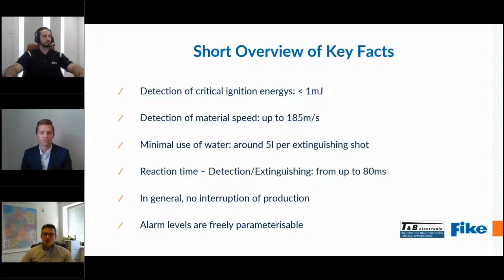Here I want to give you a short overview of some key facts. What is the critical ignition energy? It's less than 1 millijoule, and the speed of the material is up to 185 meters per second. To be honest, I've never seen any suction pipe with an airflow like this, so it won't be a problem.